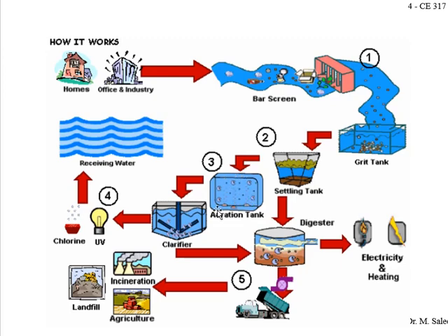In this, the wastewater is mixed in a big tank with air, right? There are bacteria which are already present; they will grow in number, and what they do is eat the waste material as food, and they take oxygen from the air and grow. So all the waste material is shifted from the water to the bacterial cells.